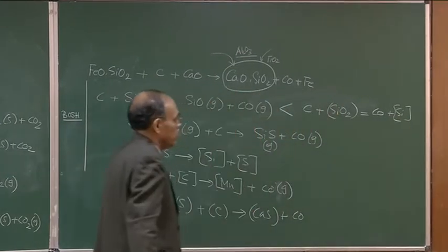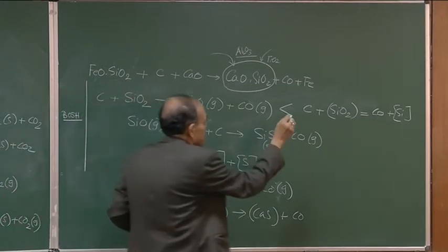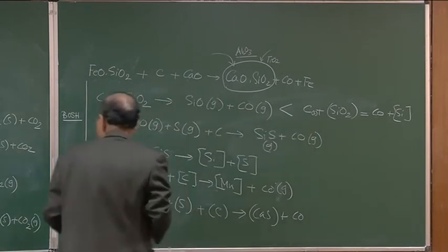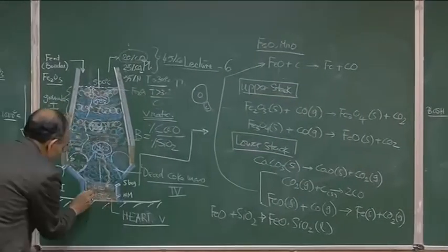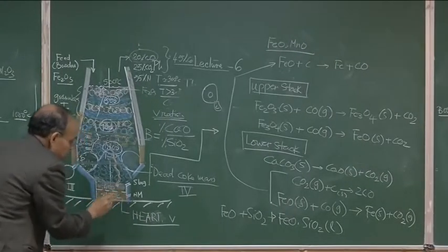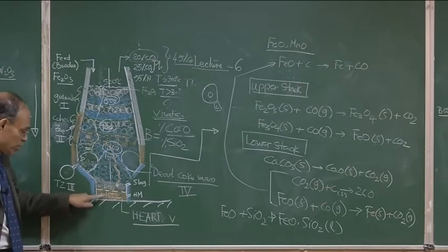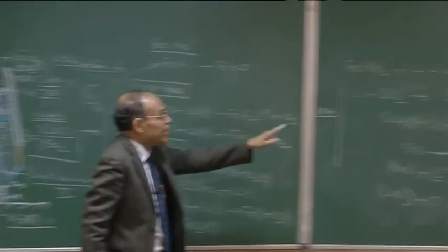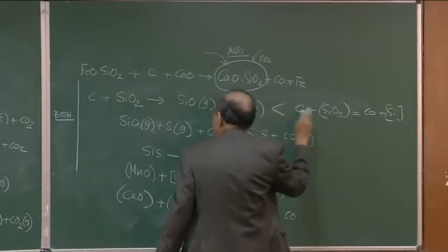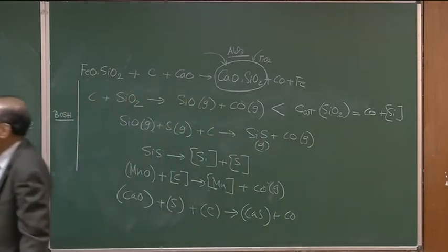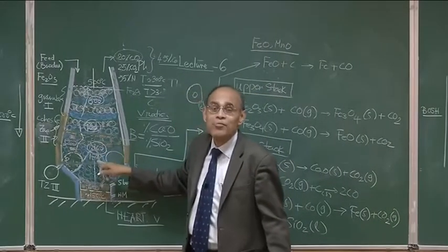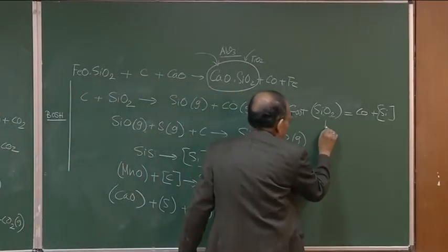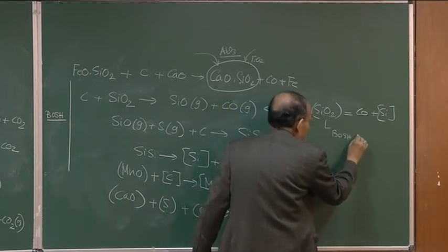Now if you write this equation, I will write that carbon is in the solid phase, or carbon could be in the dissolved phase also, with many similar reactions. If I write at this particular interface, carbon is there, as I said, the molten metal is rich with carbon, and the slag contains silica, so some silica from the slag can get reduced. This is possible at the slag metal interface. This is also possible as the slag trickles down and comes in contact. So I can say that this reaction is possible in the Bosch, and this reaction is also possible in the hearth.